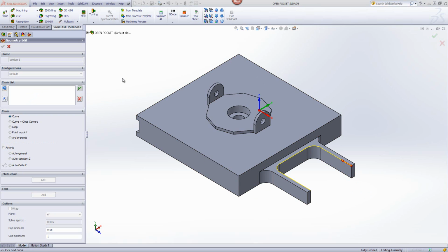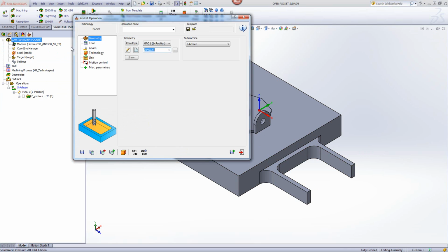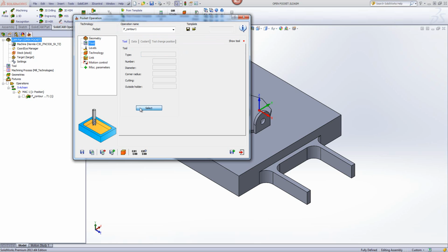Note, the moment I accept it, it's going to ask me, do I want to close it with a line? And if I do close it with a line, do I want to mark that line as open? I'm going to say yes. And what happens is we have a closed chain where this side shows that this is an open wall. I'll just accept it.